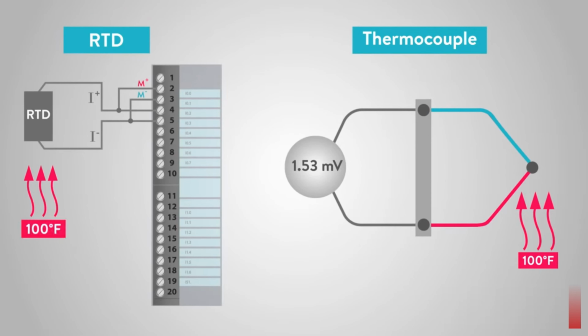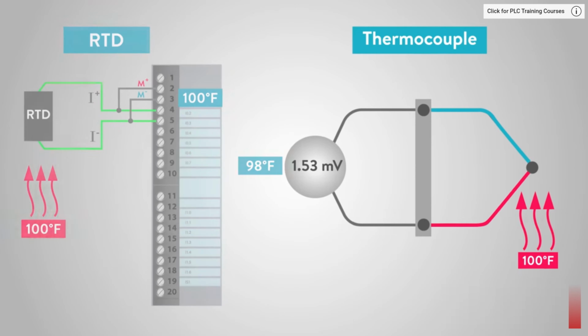In comparison with RTDs, thermocouples are self-powered and require no external excitation current source. Thermocouples are commonly used for furnaces, gas turbine combustion chambers, high-temperature exhaust ducts, etc. The main restriction of thermocouples is the accuracy, which doesn't make it the best solution for precise applications.